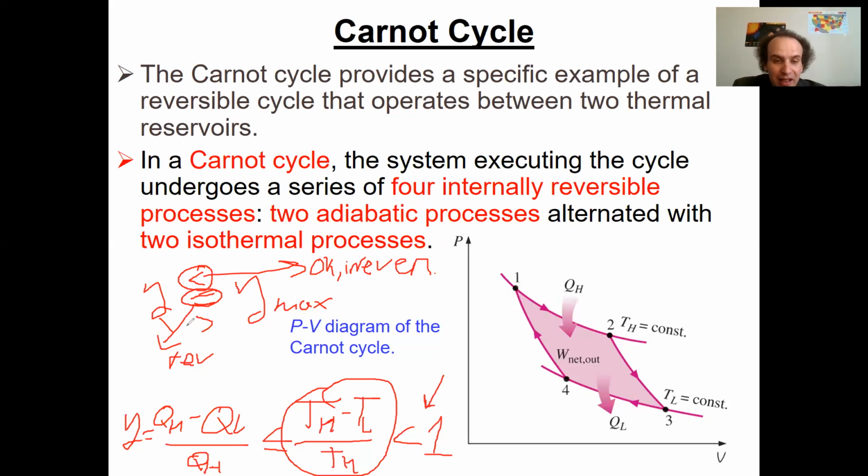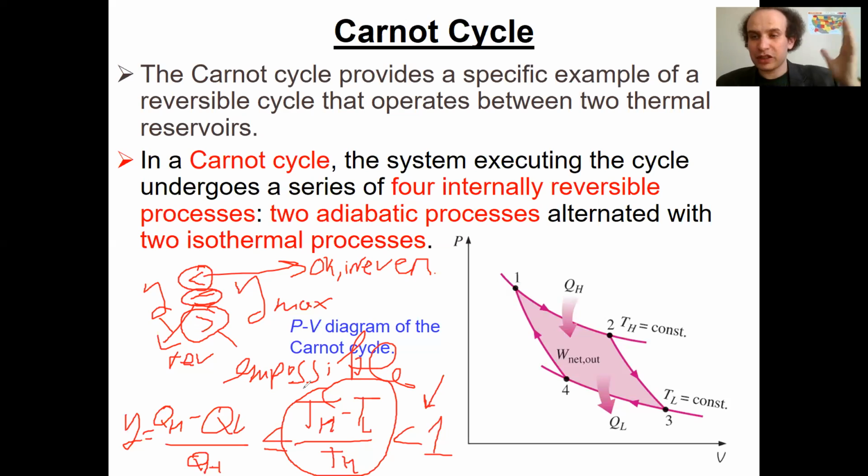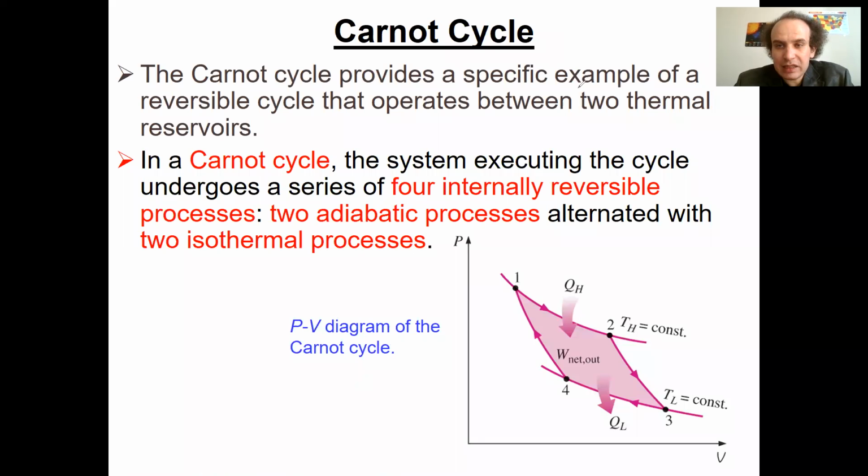So what I mean here is, if your efficiency is larger than the maximal, then it's impossible. It's impossible not because there are dissipations. Some people confuse this. It's not because there is friction. It's not because efficiency is not 100%. It's not possible according to the second law. To be possible, you should go backward to the Big Bang. Okay? Does it make sense? That's what you have in your homework.